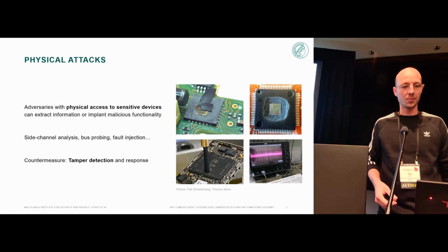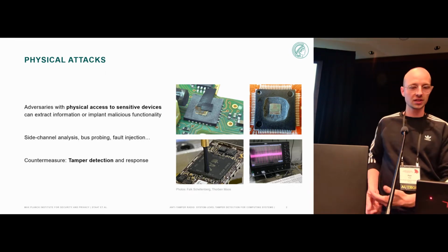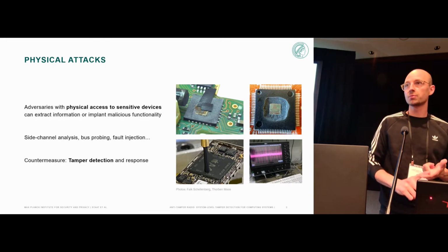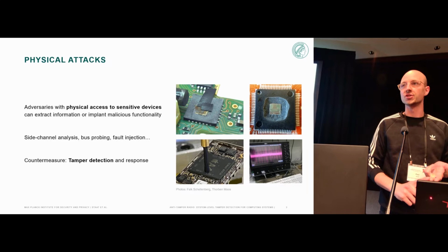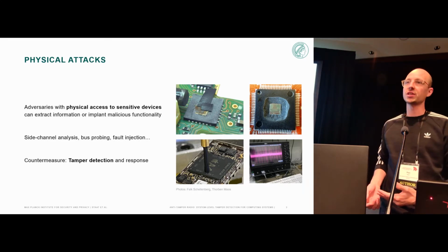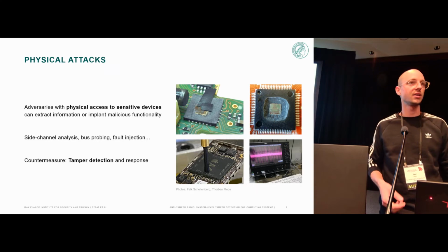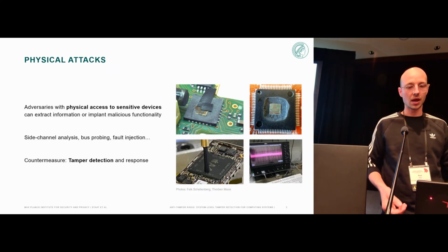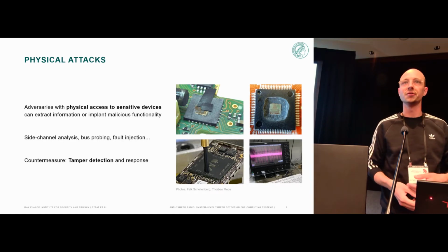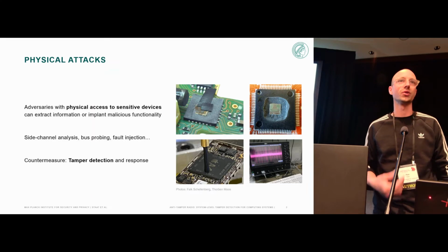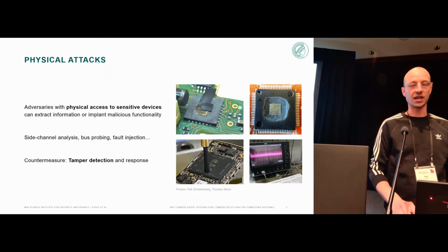The toolbox for such attacks includes, for example, side channel analysis, bus probing, or fault injection, to name a few. To counter such attacks, system designers can add tamper detection mechanisms to respond to attacks. This would then trigger some sort of self-destruction, such as the wiping of all of the critical information contained in the devices.